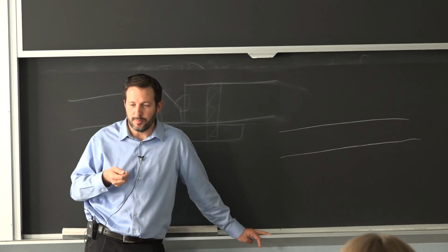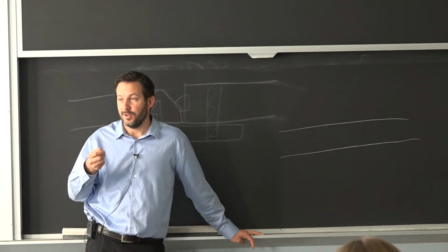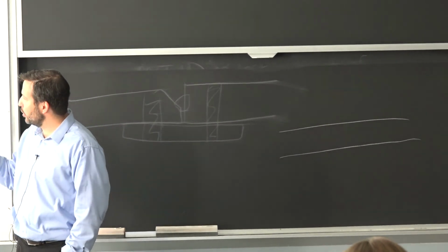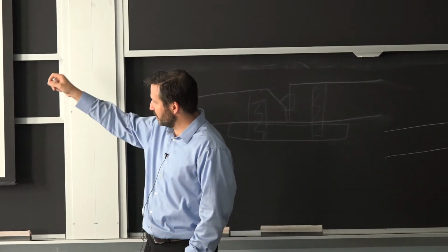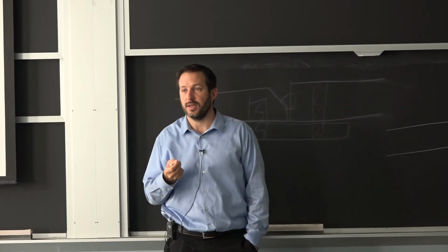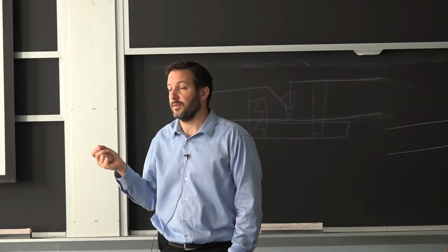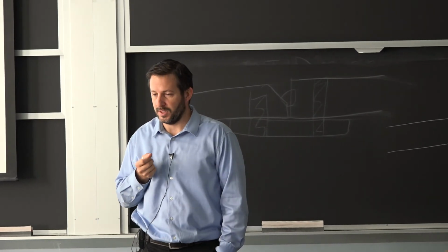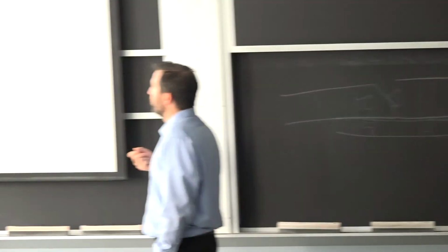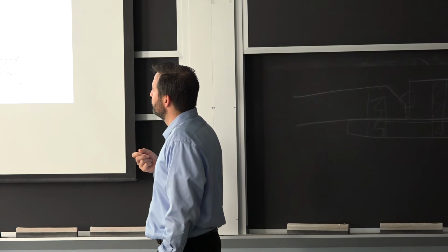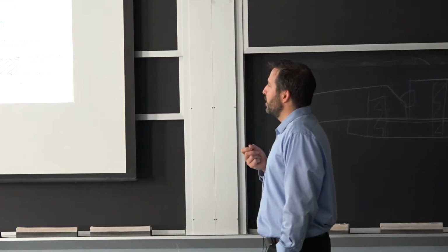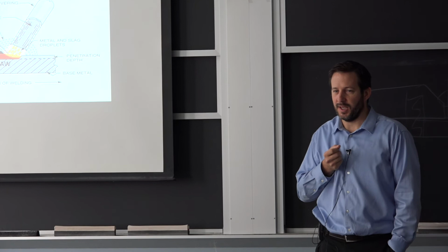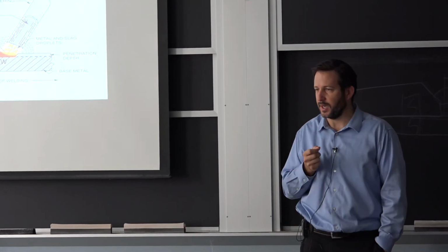So one implication of that is when you don't really have a clean surface or a clean steel composition, it's very advantageous to have a welding process just like this one that has a slag, because it will clean up. There are other processes that we'll go over that don't have this, and they do require more cleaning beforehand. So it's more forgiving here. It's the traditional way, and we'll go over what can happen and not happen. But the aspect of melting the steel and protecting the environment to some extent, if you do it right, it's all good.